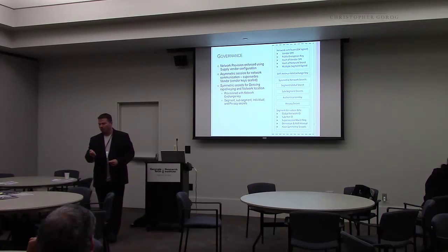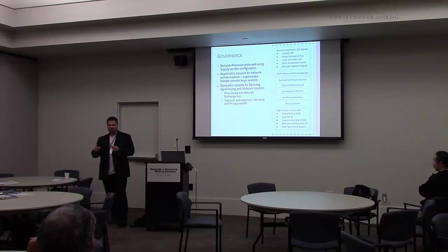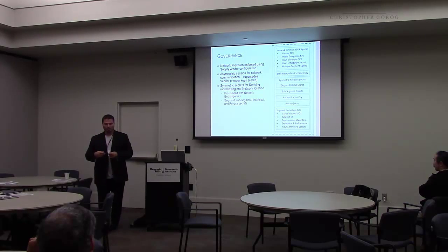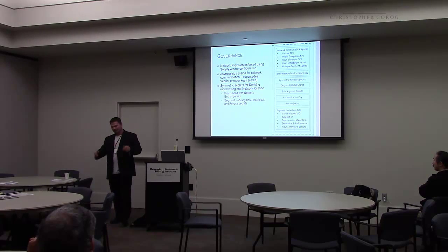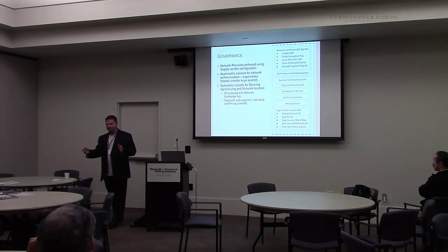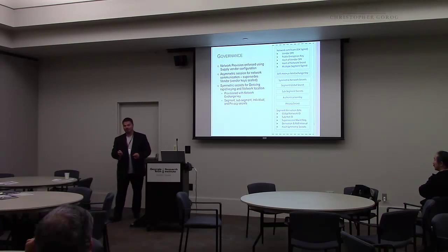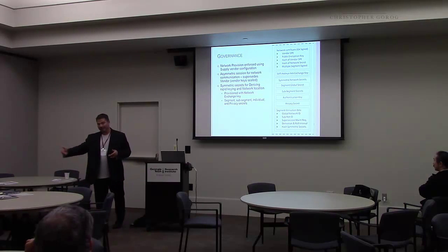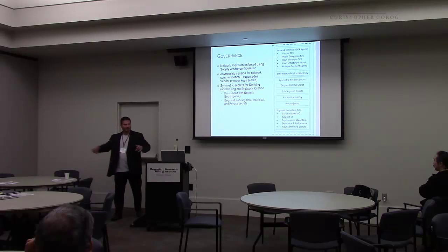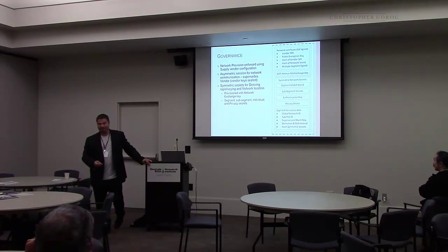Anybody familiar with how a garage door opener works? Whenever you click the button, it communicates with the receiver, which synced with it last time. You click the button, it does the operation, and it says roll to the next key on both ends. So both ends now roll from one key to the next, and it's just a big long key, and they mathematically put in an increment number, sometimes just 1, 2, 3, 4. So if you've hit the button 1,000 times over the life, you're on the 1,000th roll of the new key. Now both ends are doing the same thing, and they both can do this at two different points and multiple points, and they can come up with the same number, but there's no way you could calculate what that number is after 10 years.